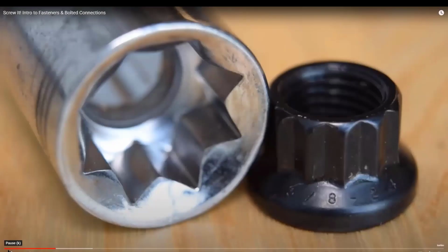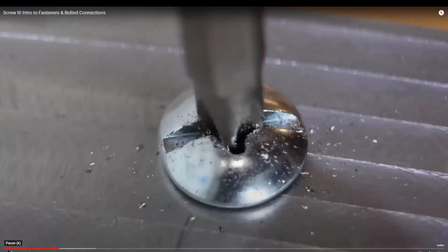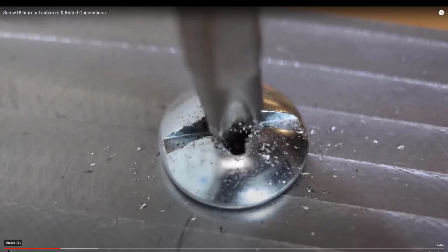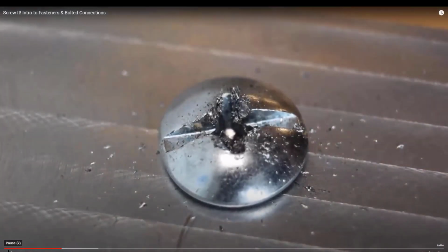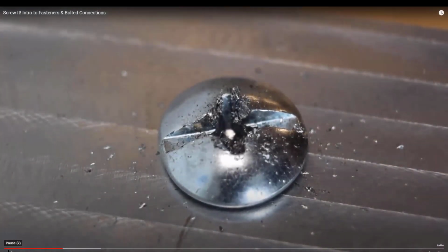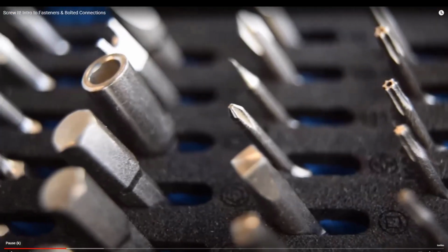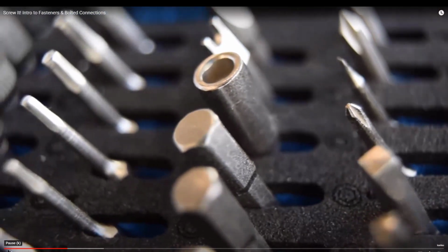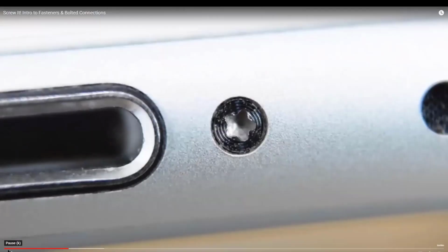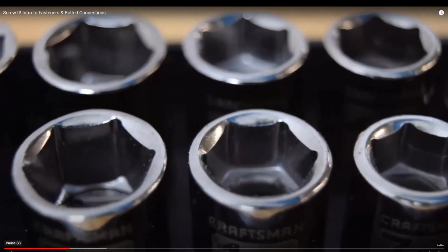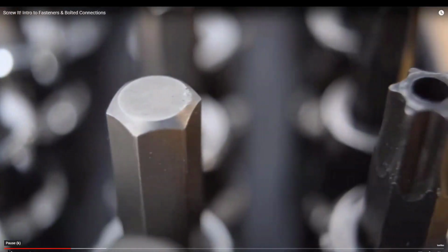High-strength nuts and screws are sometimes manufactured with an external 12-point drive, which offers more points of contact than the traditional 6-point hex. It's best to avoid Phillips and slotted drives if you can. While being widely available, they are subject to cam out and can strip easily. Even the construction industry is moving to Torx drive because of the many advantages. There's also a lot of really oddball drive types that were designed for very specific applications or to purposely be obscure. Unless your design fits into these categories, you should probably consider something more mainstream.